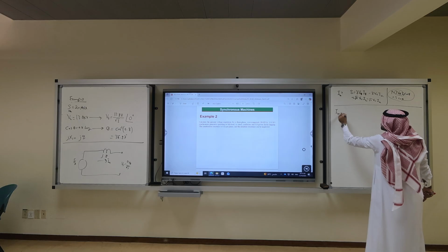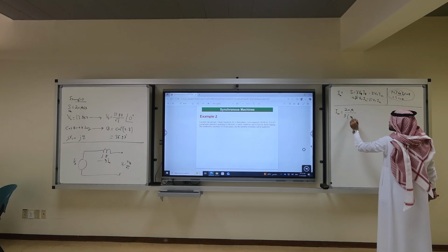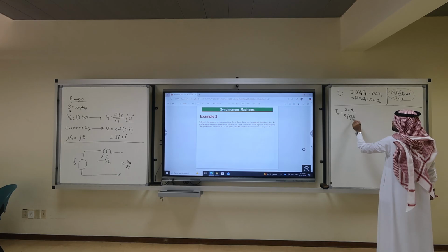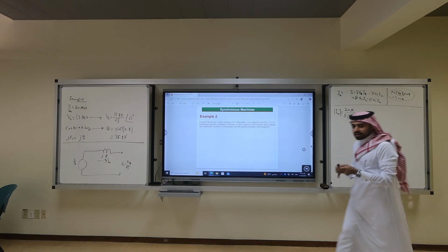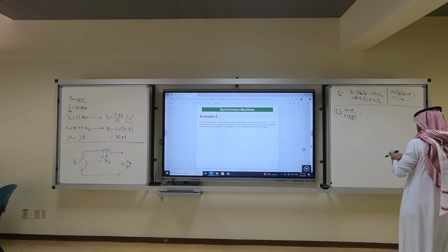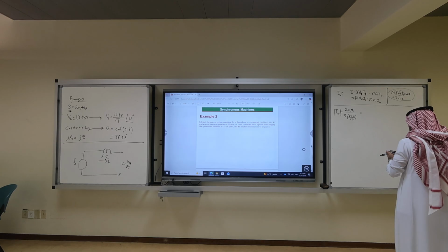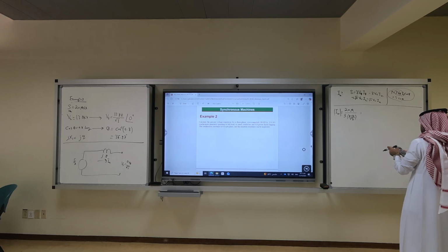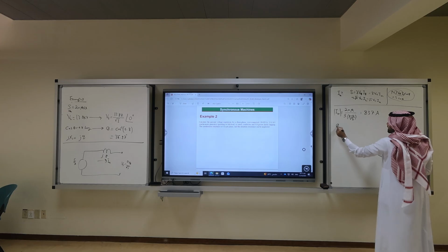So what is IA? Is it 20 mega over 3 times 13.8 kilo over square root of 3? This is only magnitude, remember? What's the IA magnitude? Calculators, please. 20 mega divided by 3 times 13.8 kilo divided by square root of 3. What is the answer? 837 amps.